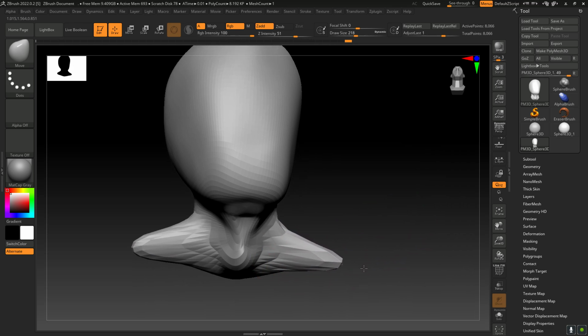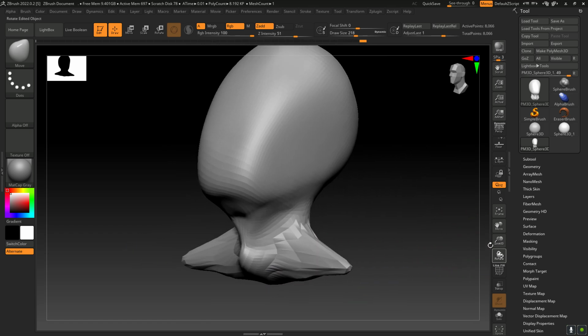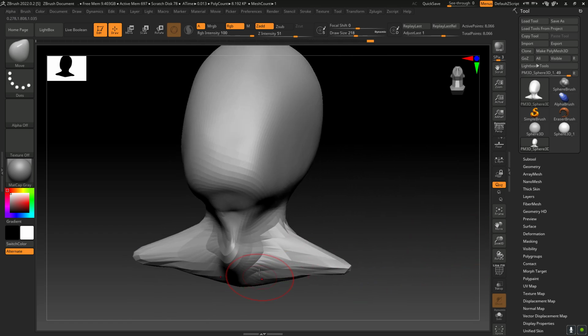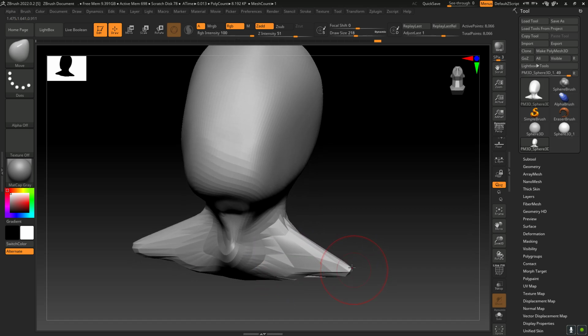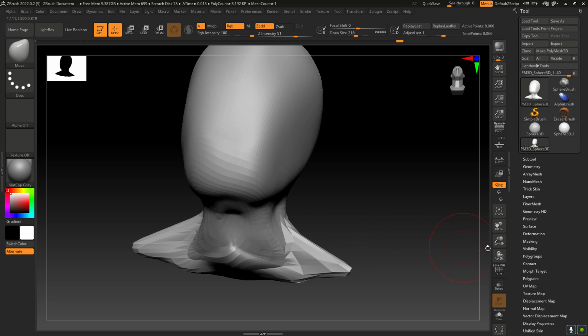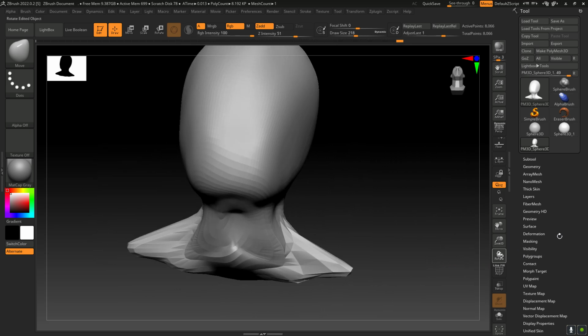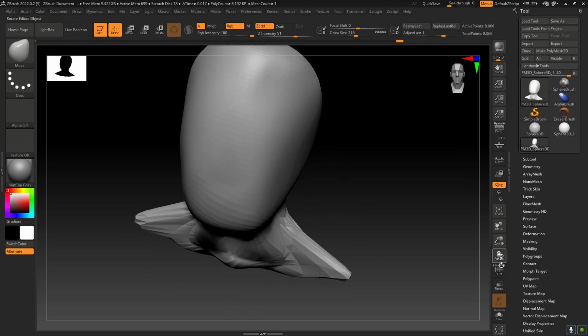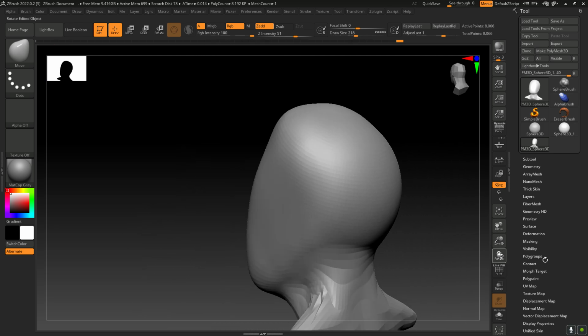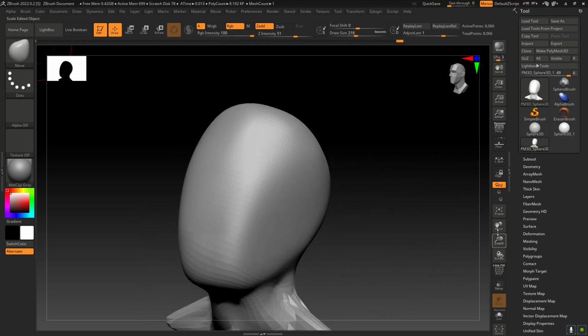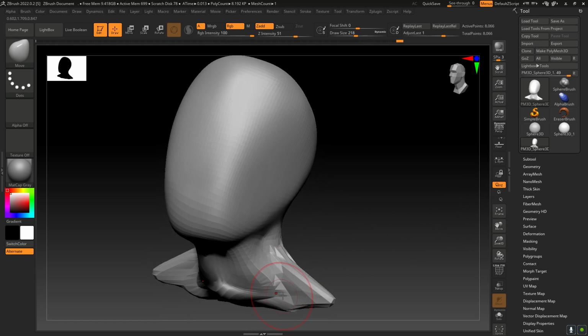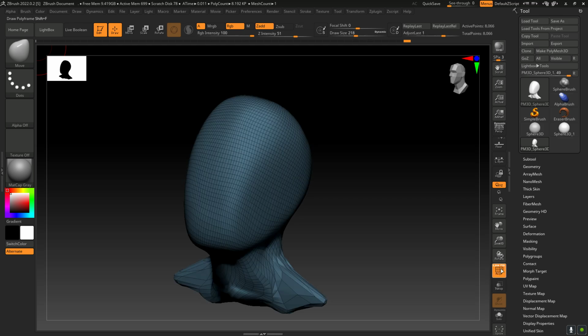When you are increasing, your polygons are increasing. Can you see this? It is stretching the polygons, right? Yes or no? Stretching the polygons. So how do we make that even smoother? How to bring that mesh? That is Control D. Control D is increasing the division of the mesh.